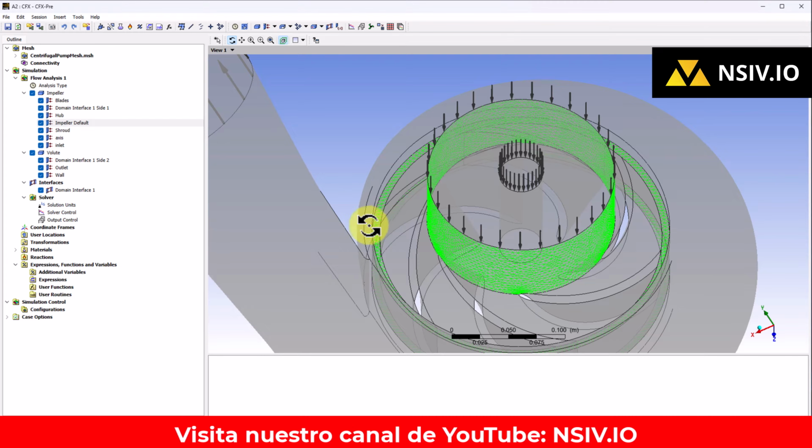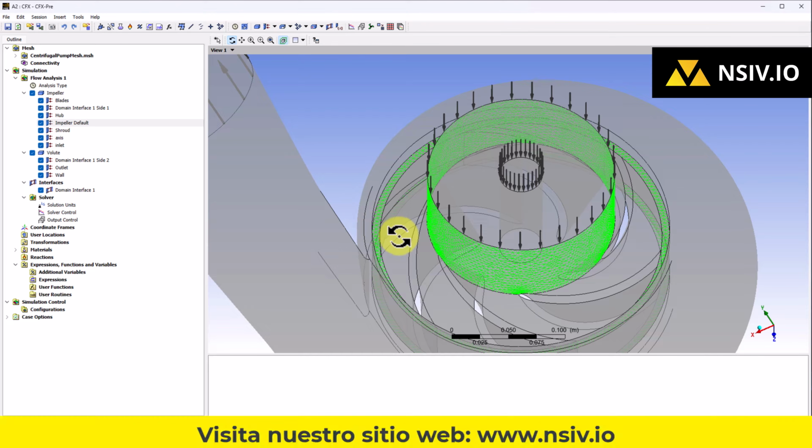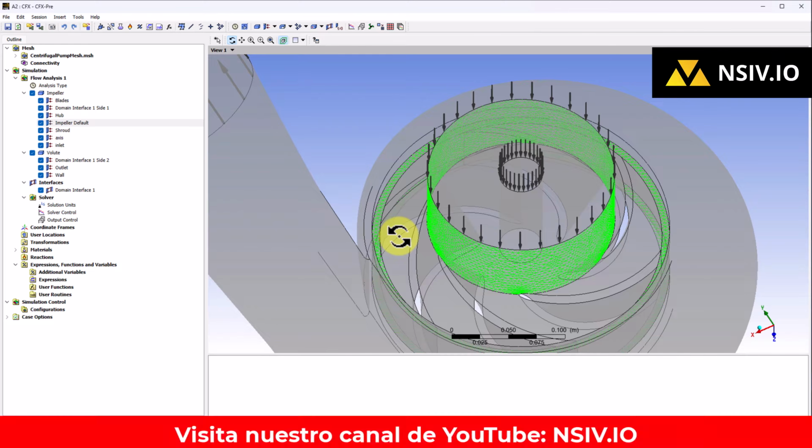Right, and this small space here is called tip, which is the space between the impeller and, let's say, the connection it would have with the volute. That is not going to move either, they are fixed zones. But within it the flow will be moving at the corresponding speed. So since that zone is fixed but belongs to the impeller, we must make a configuration to counteract the angular speed of the impeller. How do we do that?